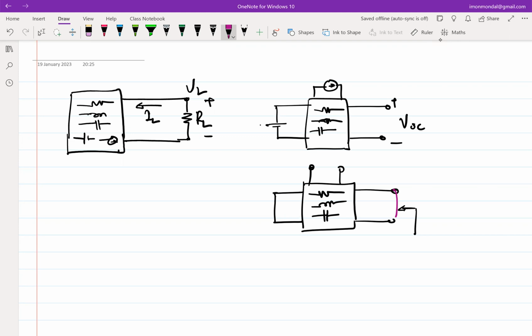Yeah, a multimeter gives you the answer, right? But a multimeter operates on a principle. I'm asking for the principle. Let's say you have voltage and current sources available in the lab. So how will you figure out an impedance? What you said initially was correct, right? So you'll have to essentially apply a voltage source here and put maybe an ammeter here and figure out what is the current going through it. You know the voltage that you have applied and you find out the current, and divide. Right? So essentially that's how you'll get an impedance.